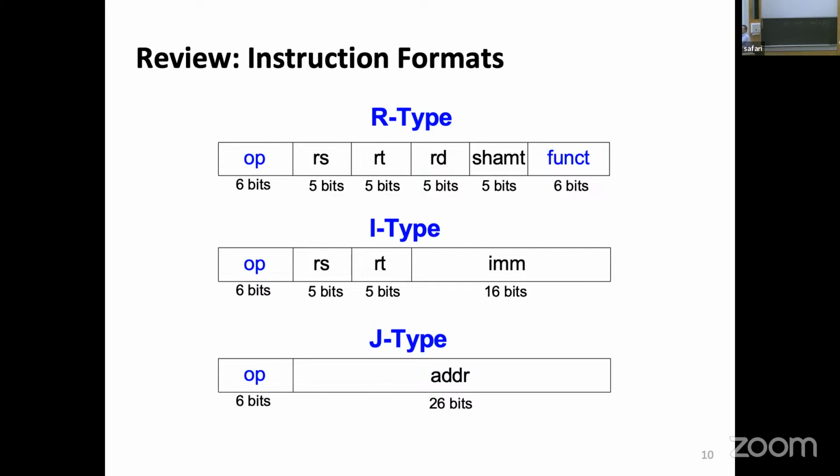Say what? Every data in the memory has a location. That location is a 32-bit address. And instead of writing directly the address, we are using a lot of indirection here. First, we say, look, there's a base register. Whatever is in S0, let's read this out. And on top of that, let's add this constant, in this case, 44.